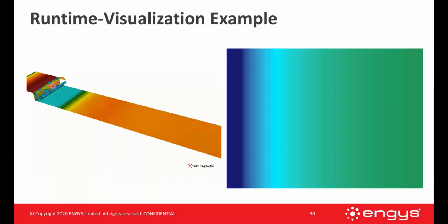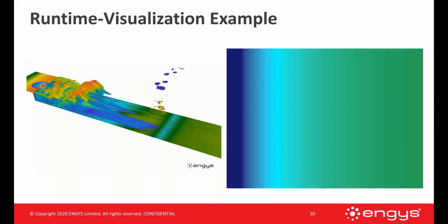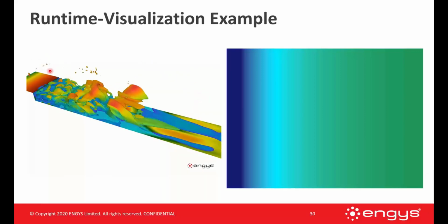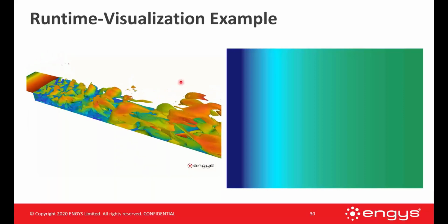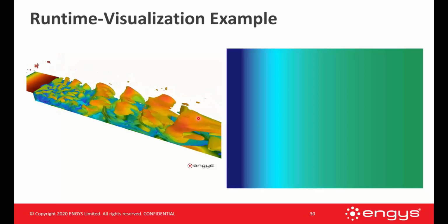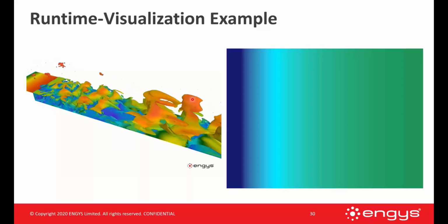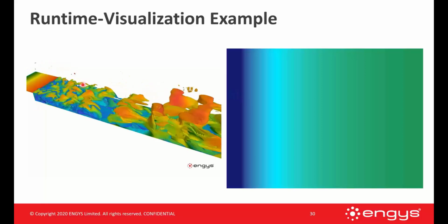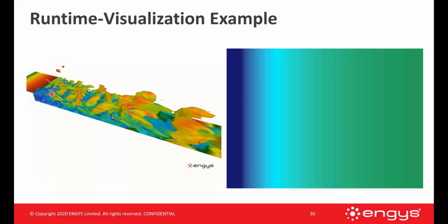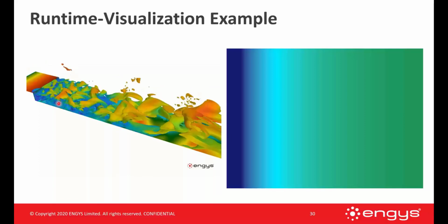So here on the left, we are able to capture these isosurfaces of vorticity that are generated, and we see some shedding of these vortices at the top of the domain. And then at the beginning of the simulation, you saw a little bit of vorticity generated from this wave of flow coming through the simulation. So we can see this turbulence being generated at the trailing edge of this backward facing step.